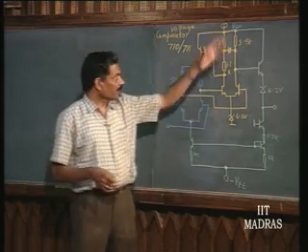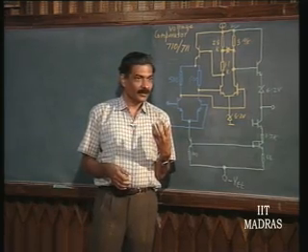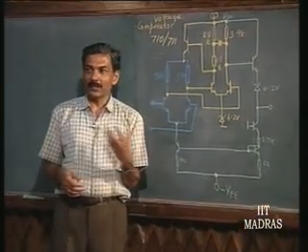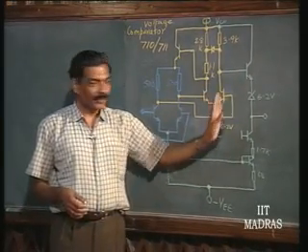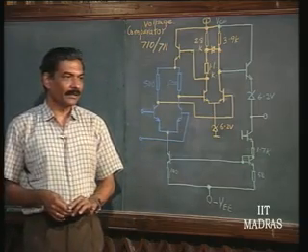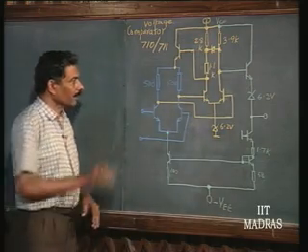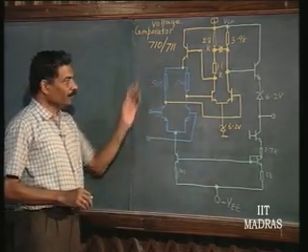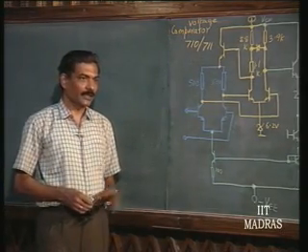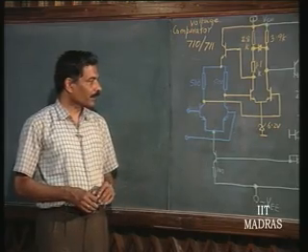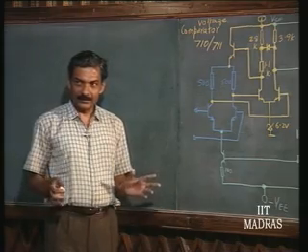When this comparator 710, 711 became popular, TTL circuits were in great use in almost all digital designs. And therefore, this was designed with output level becoming totally compatible with that of the TTL logic family. So, that is as far as the output is concerned. The input is still the differential amplifier stage, no doubt, like in the case of a conventional op amp. But once again its responsibility is different.